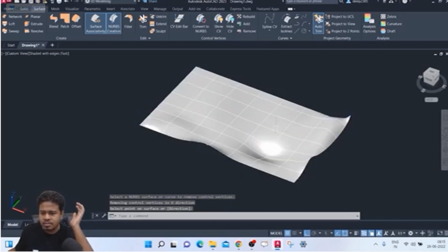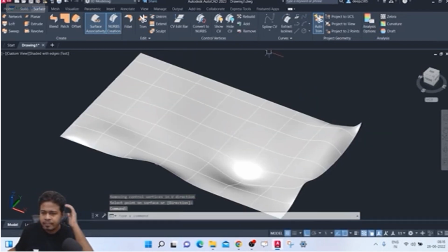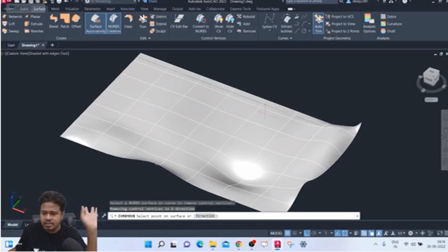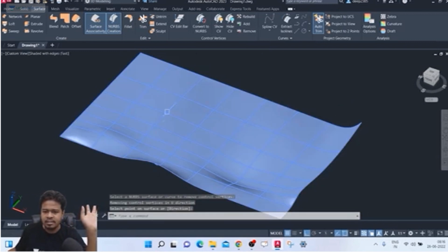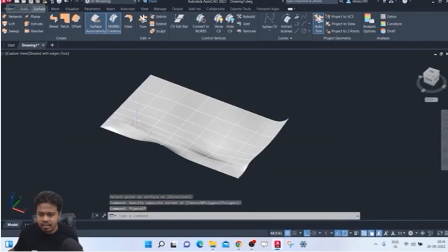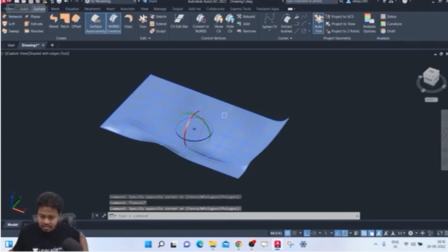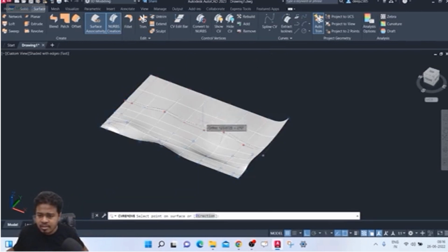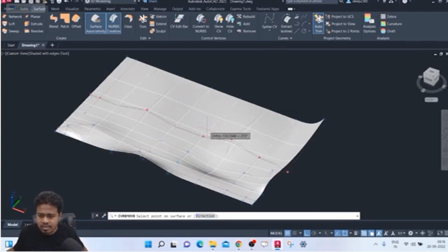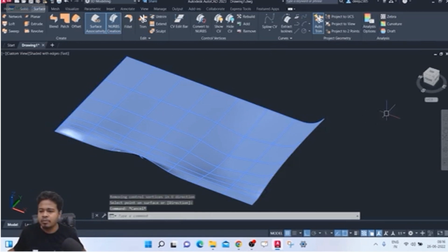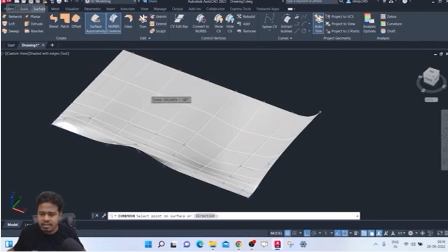So see, that has been removed. Okay, go to remove, select this. Slowly, the control vertices line is getting removed. Go to remove. Suppose I want to remove this. So select here. So it will be removed. So like this it works. Go to remove again. Select here.